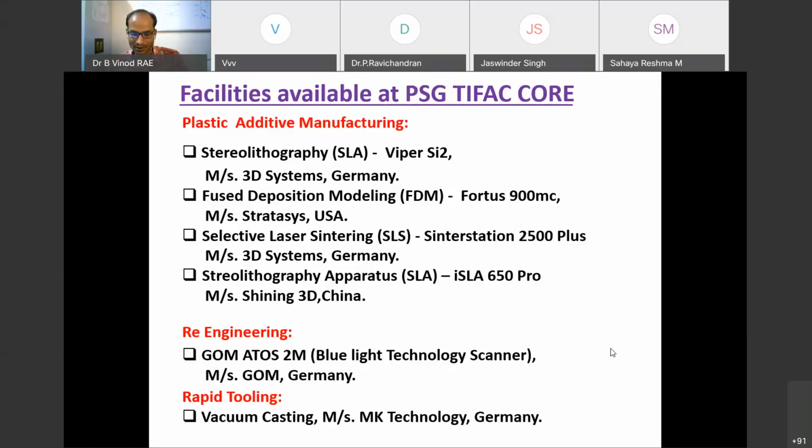Five material options are available: ABS plastic, polycarbonate, ABS, ULTEM and PPSF. These ULTEM and PPSF are high temperature withstand materials. Maximum they can withstand 180 to 200 degrees Celsius. Mostly useful for the aerospace and defense sector.